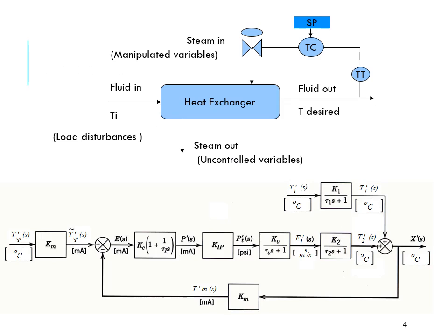What we have learned in the previous session is the components of the control loop. It consists of the transmitter signal, then the controller, and also the final control element. In order to design a control system, we need to identify certain variables that are the control variable, the manipulated variable, and also the disturbance.